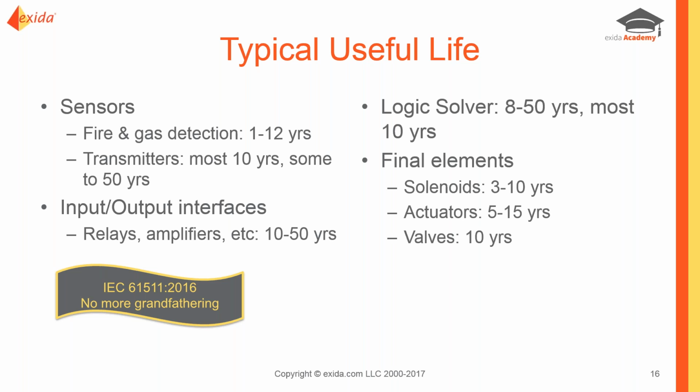As for the logic solvers, for most logic solvers about 10 years is a typical useful life. Again, there are a few that are qualified for a longer useful life. And then the final elements are really our weak point in setting our timeline. Solenoids, valves, and actuators do tend to have a much shorter useful life. They do wear out. You can see solenoids even down in the 3-year range.